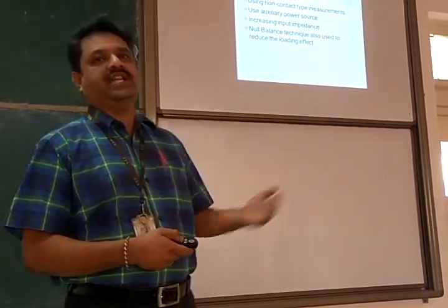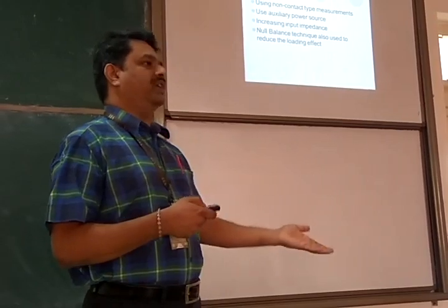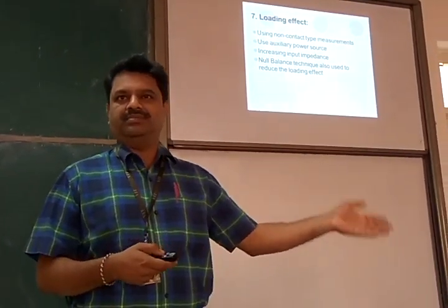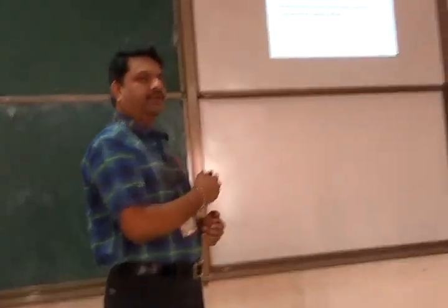So you basically don't touch the rotating shaft. You don't disturb it, which means you don't load the system. So no loading effect will be there. That way, with non-contact measurements, you will be able to measure better.